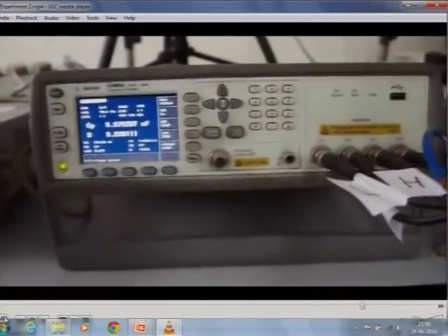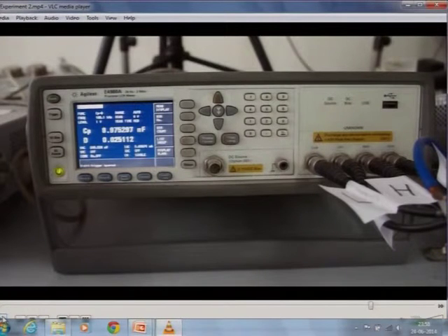The readings for this experiment are captured by an LCR meter. This is the instrument which is used for capturing the data. This instrument is called LCR, and it is used for the experiments which are based on the EMI technique. It captures the conductance and the susceptance signatures of the PZT patch, and this LCR meter is also connected to the user's computer via internet through vPro software. So, in this experiment also you need vPro software to perform the experiment.